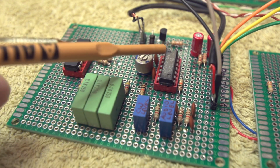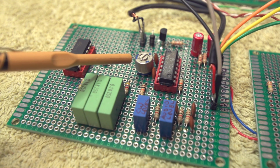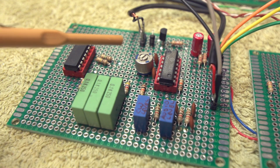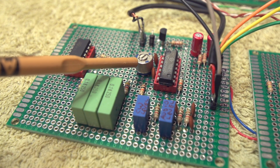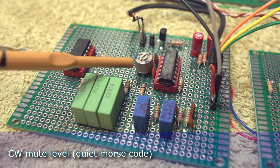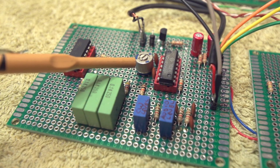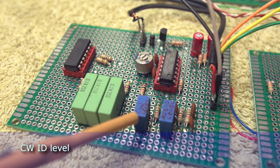So here we are with our 4066 here. You'll notice there's a few preset controls. There's one there, another one there, another one there. So this preset here is adjusting the mute level. When the CPU card sends a mute signal through one of these wires here, it basically reduces the audio volume of the CW ident, so it's kind of in the background while somebody else is talking over the top of the repeater. This control here is the overall CW level.